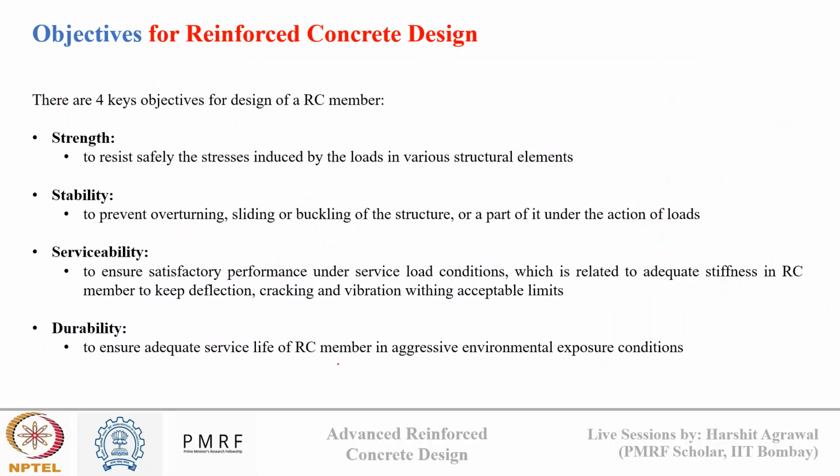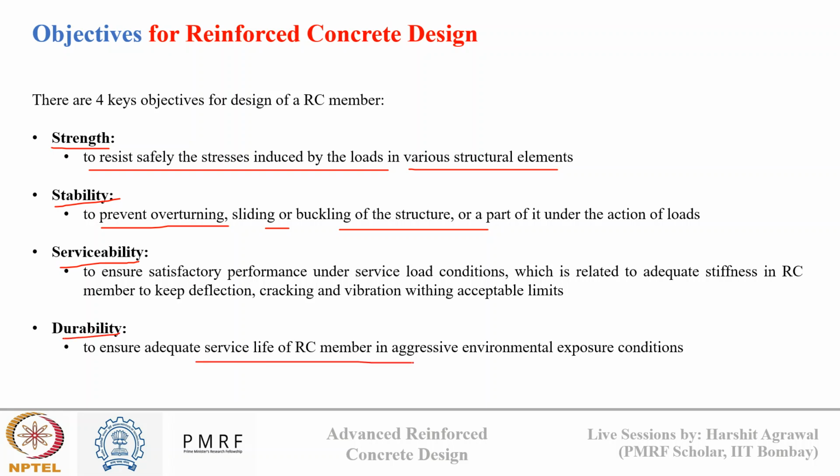Now, there are four key objectives of reinforced concrete design. Okay, what are these objectives? First is strength, which resists safely the stresses induced by loads in various structural elements. Then there is stability to prevent any kind of overturning, sliding, or buckling of the structure. There is serviceability to ensure that the performance of my building is satisfactory over time, and then durability to ensure that the service life of my building or my RC structure is maintained even in aggressive conditions. Okay, so to achieve these four key objectives, design is needed.